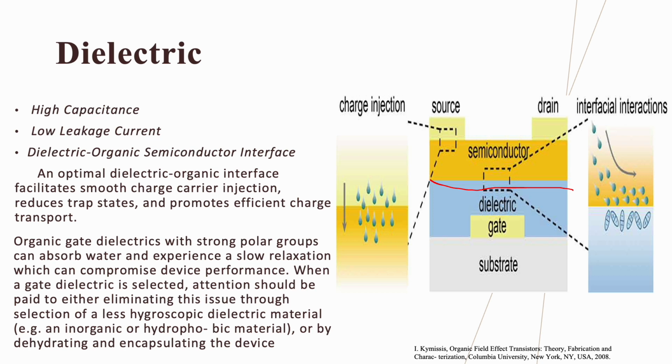The mobility of the charge carriers in organic semiconductors is relatively low compared with traditional inorganic semiconductors, and it is influenced by factors like the molecular structure, crystallinity, and temperature. In some cases, charge transport may occur by hopping between localized states or by delocalized charge transport along conjugated polymer chains.